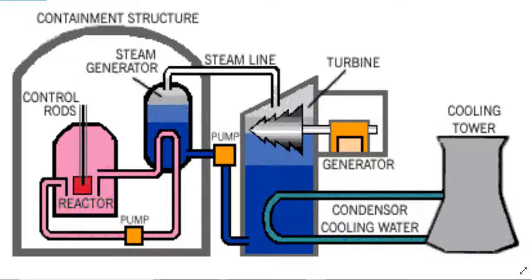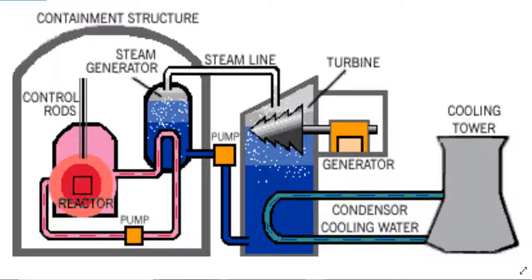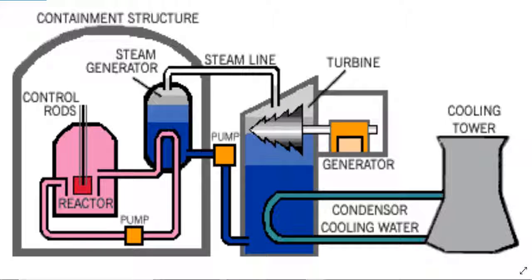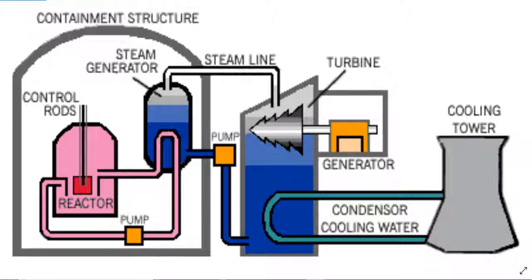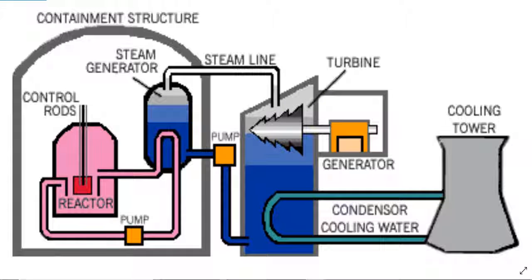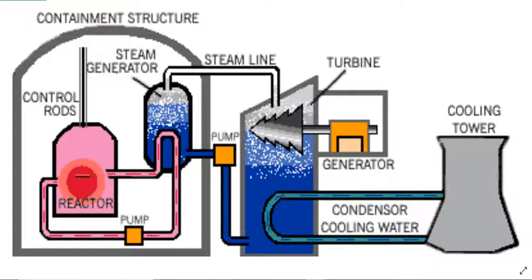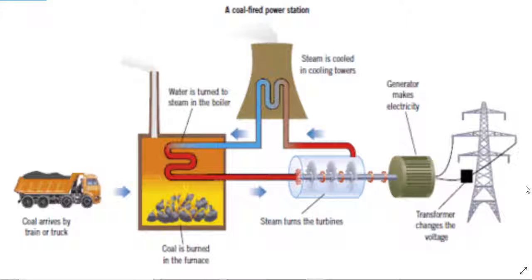Combustion gas turbines, which are similar to jet engines, burn gaseous or liquid fuels to produce hot gases to turn the blades in the turbine. Steam and combustion turbines can be operated as standalone generators in a single cycle or combined in a sequential combined cycle. Combined cycle systems use combustion gases from one turbine to generate more electricity in another turbine. Most combined cycle systems have separate generators for each turbine. In single-shaft combined cycle systems, both turbines may drive a single generator.